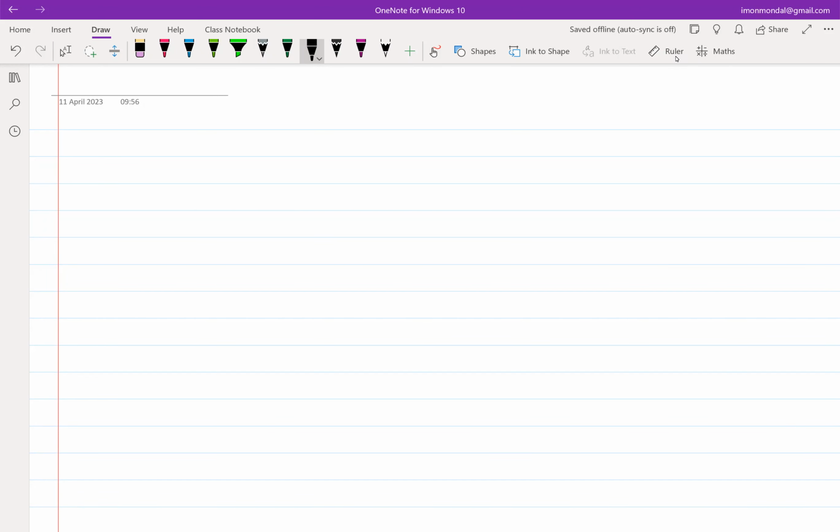So, before we went into the diversion of PMOS, we were doing all those things because we wanted to get a high gain amplifier. And why do we need a high gain amplifier? Because we need a high gain amplifier to realize a negative feedback loop. And why do we need a negative feedback loop? It's because we want to ensure that whatever gain, low or high, we get should be independent of any variations. Right. And that's how we went about doing it. And this is the structure that we were looking into before we went into the diversion.